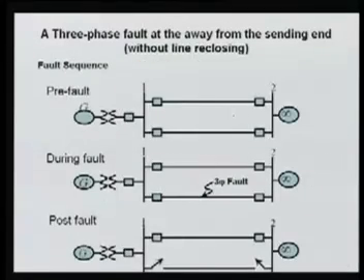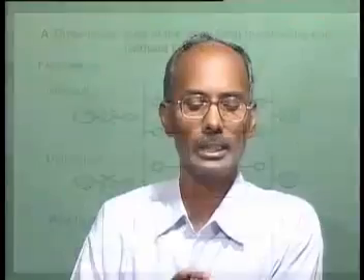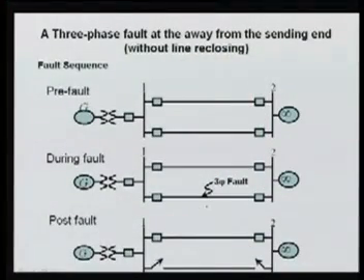Let us now consider the three-phase fault in different scenarios. So far we have discussed the three-phase fault occurring at bus 1, but let us say a fault is occurring in the line, followed by the tripping of the line. During the pre-fault, the system is the same as in the previous slides: generator, generating transformer, 2 lines, connected to the infinite bus system.